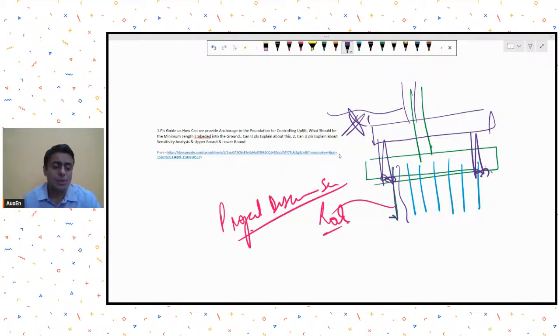So in such situations, you may go for anchoring using friction piles. And if you already have a hard strata, if rock anchoring is possible, as I just told you, you can go to the project discussion series episode 1 that is there on our YouTube channel. You will get some sense of what I want to tell you.